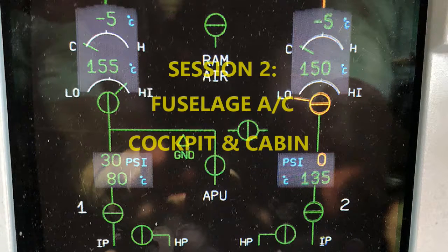And of course, there are safety valves along with this part of what we're talking about on the pressurization. So there are 2 safety valves that are installed in the aft pressure bulkhead to prevent, of course, too much either way, either positive or negative pressure in the fuselage, in case there's some kind of malfunction with the control system. So those safety valves are there. As you know, we always have safety valves, in case we have a failure somewhere.